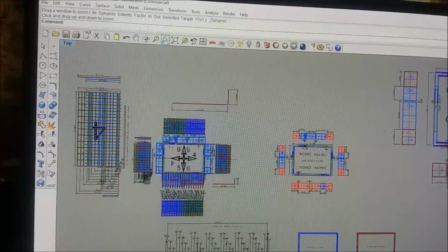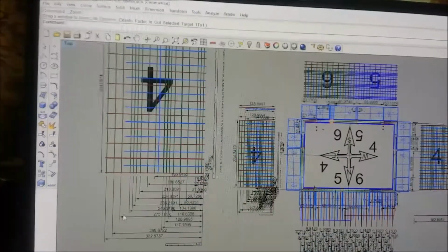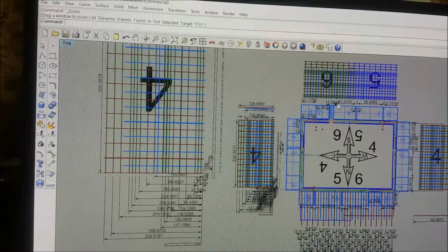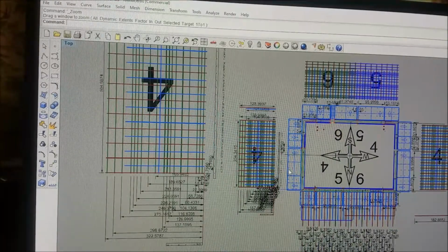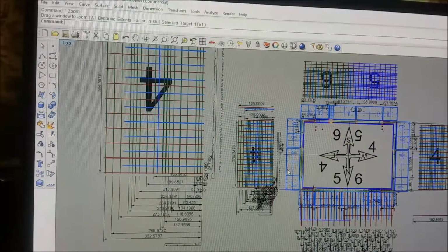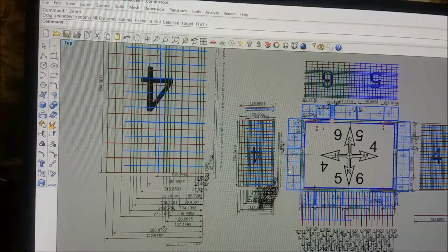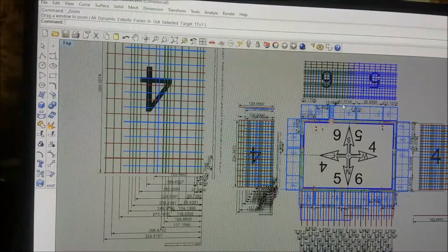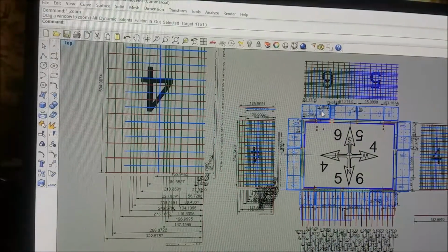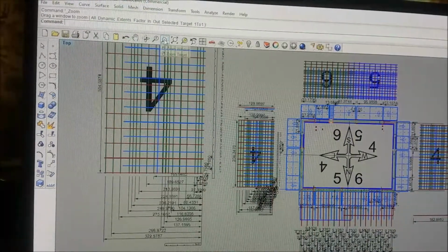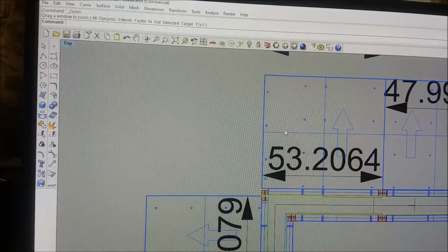For our foreman, we give him drawings printed off, and this shows the length of the individual slip forms. These slip forms are for the septic tank, the water cistern, fish pond, mausoleum, dirty kitchen. And that's why we have an 81-inch form instead of a 96 up here, because that's needed in the dirty kitchen. And we have some 4-foot sections, just because it allows us to do any of those things we want to build without building new forms. The forms for the system are basically all the forms we own.